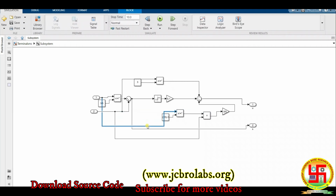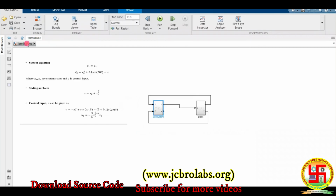So this is the block, this is the Simulink diagram for basically the control input. So we have got here, first we have taken the sliding surface, that is a combination of x1 and x2, that is x2 plus x1 raised to 3 by 5, that is the sliding surface.